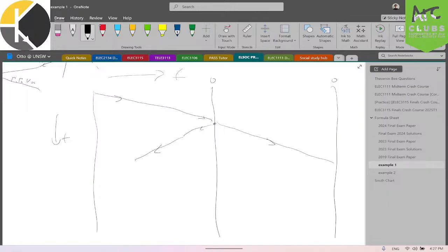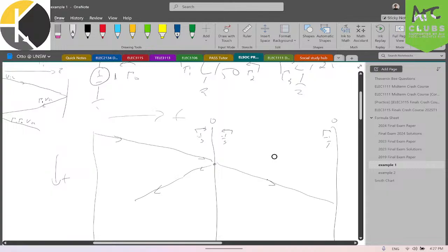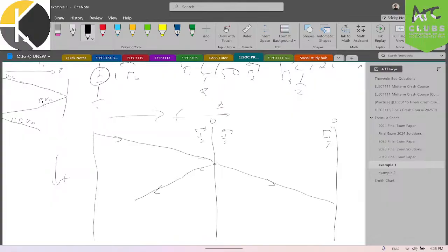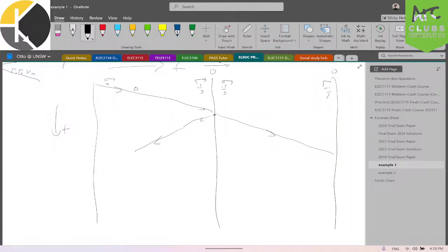Okay, so gamma this way is 1/3, gamma this way is 1/3, with minus sign, gamma this way is minus 1/3. And the transmission coefficient, T, is going to be just 1 plus gamma, so it's 2/3. Right? And the reflection here is 0. So what's going to happen? Like the first wave goes through, it reflects from the interface. The magnitude of the first wave is going to be 0.5.